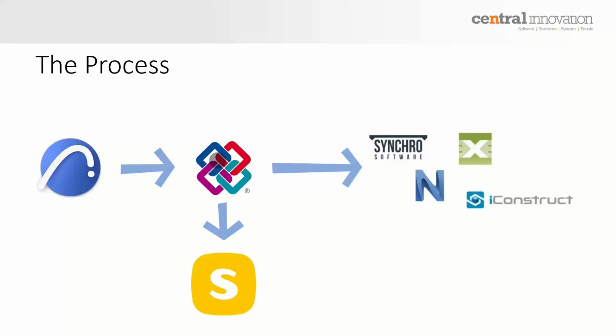Now, as I mentioned a minute ago, we may also need to adjust the actual model so that it works for construction sequencing. In general, we recommend that the model be checked, even if it's just briefly, in Solibri or any other Ifc viewer for the purpose of validating the model before you send it out. And then, of course, the purpose-built software application will take care of the actual simulation.